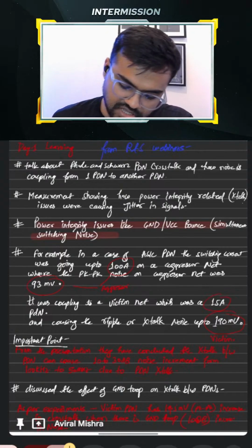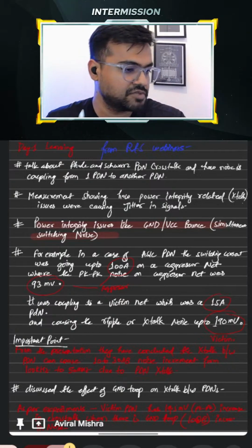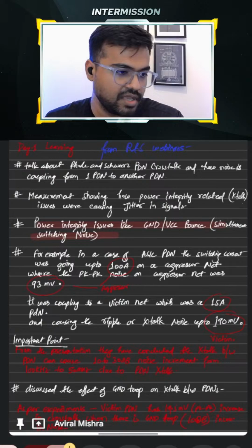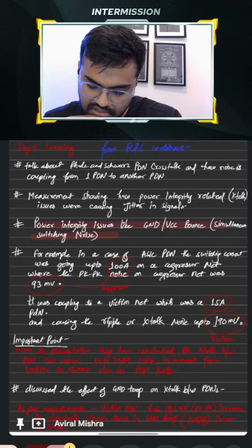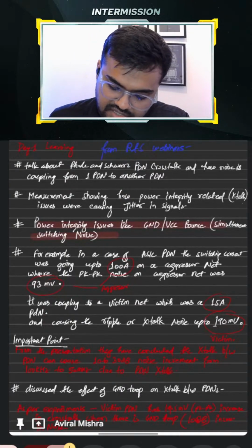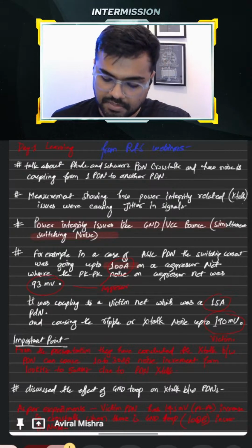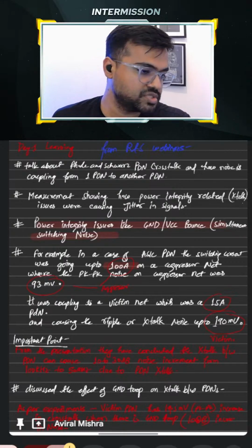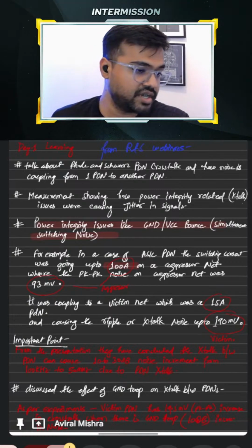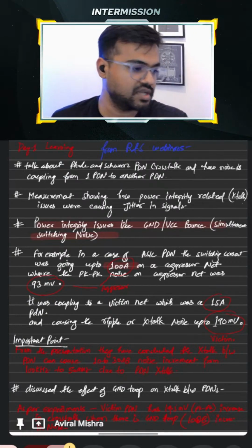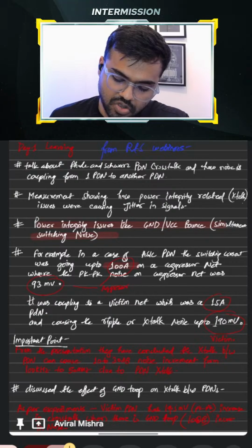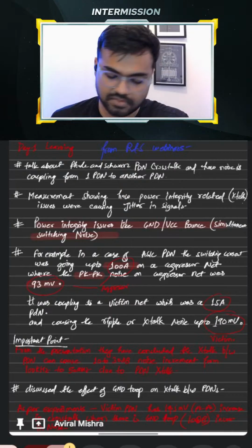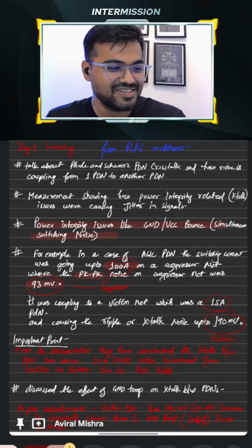They've also talked about a couple of examples, and they were showing the proper setup where they were probing some ASIC boards, right? And there the aggressor current was going up to 100 amps. I'm talking about the switching power supply. The current was going up to 100 amps, which we know happens in the case of an ASIC. So that was the aggressor. And on the aggressor, the peak to peak noise was around 93 millivolt, right?